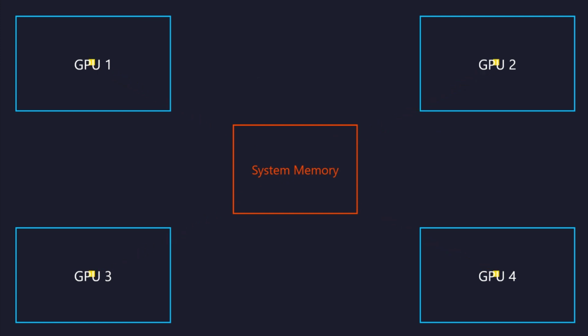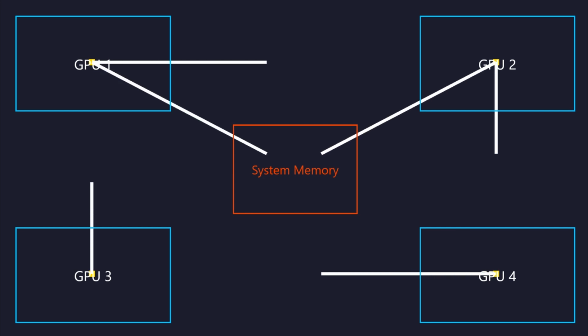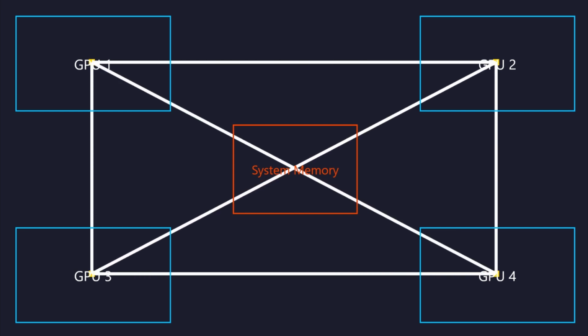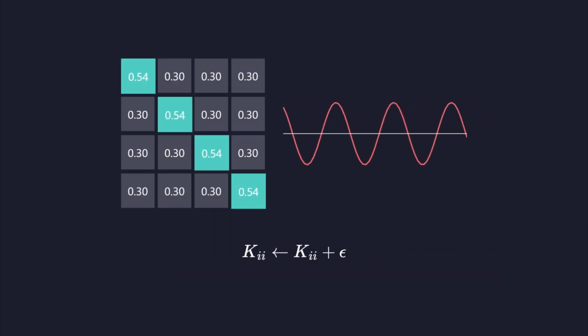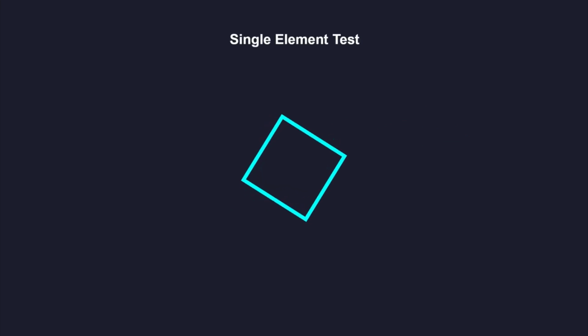For massive models, distribute the element blocks across multiple graphics processing units. Use peer-to-peer communication over the high-speed interconnect to share state variables without involving the system memory. Poorly conditioned tangent matrices lead to solver failure. Add a small regularization term to the diagonal of your neural tangent matrix to improve the condition number without significantly altering the physics of the material response.